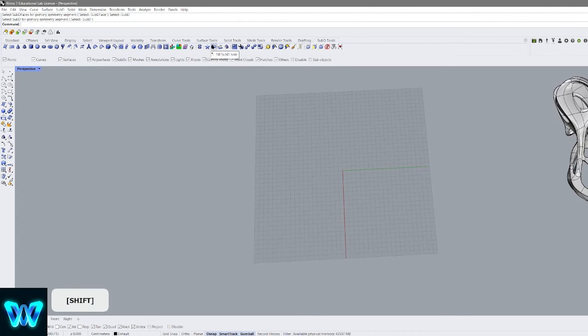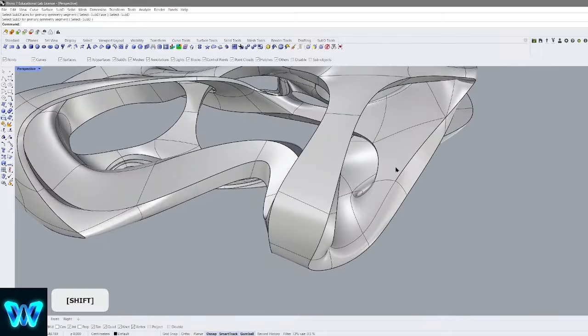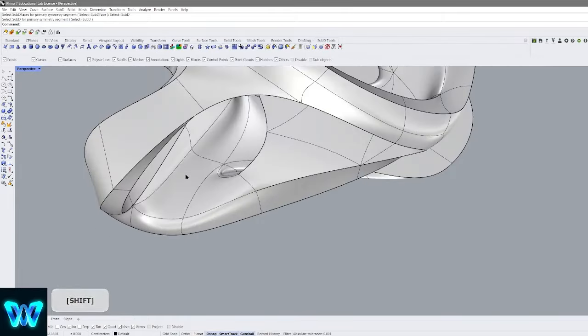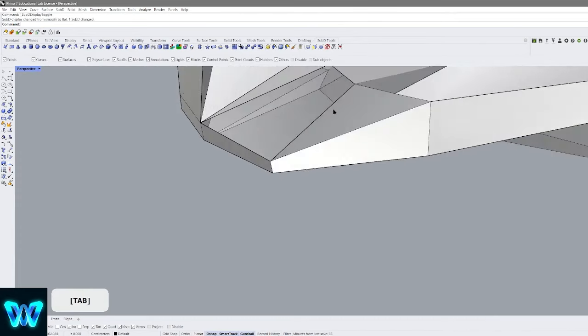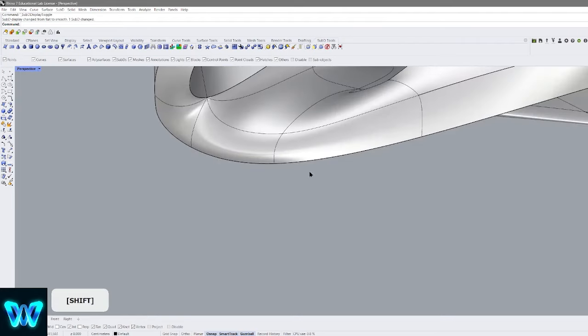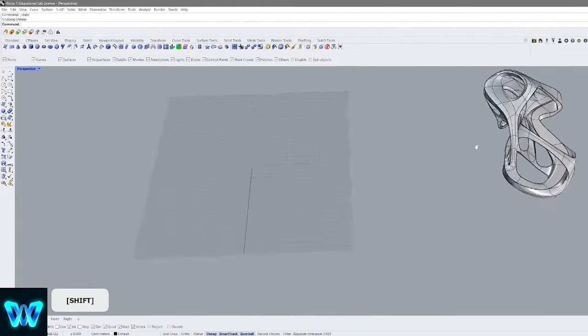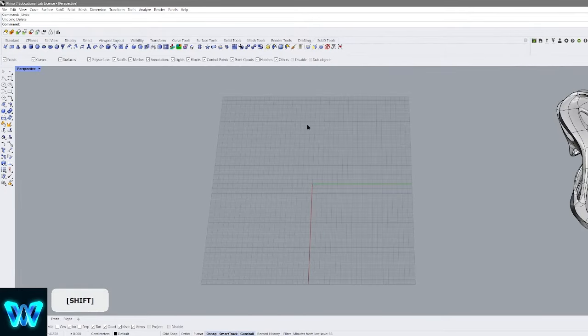And then you get into SubD fill hole. This is one of the other ways where you can fix things, like I was mentioning before. Or for example, if you have something that's gone, a hole, you can just fill it. So if you just select the edges, select fill hole, it will fill it up. And it's back to its state. So that works pretty good just to start fixing things around.